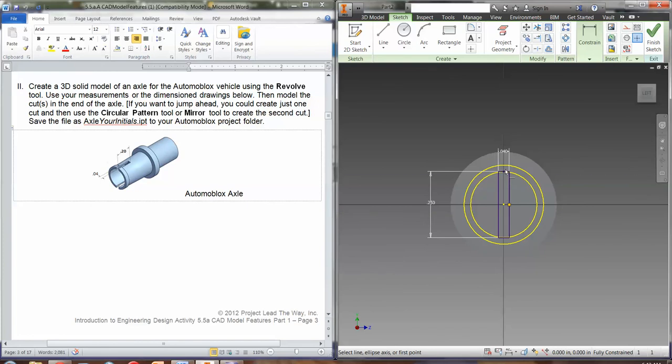And that gets it back up, but it's not reaching all the way. So escape to get out. We're going to double click this 0.25 measurement. Let's change that to a 0.35. And that extends past, and that's good. That's what we need. So we've got our dimensions on there.